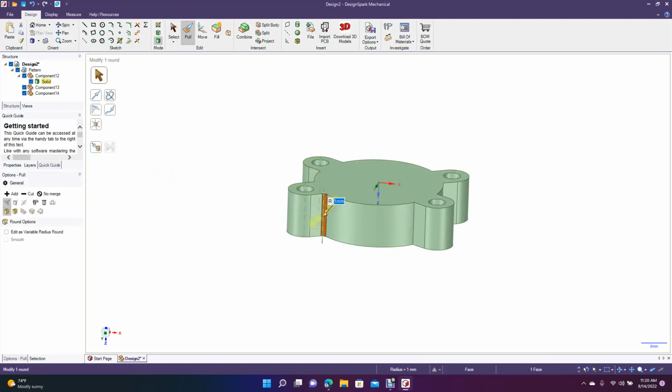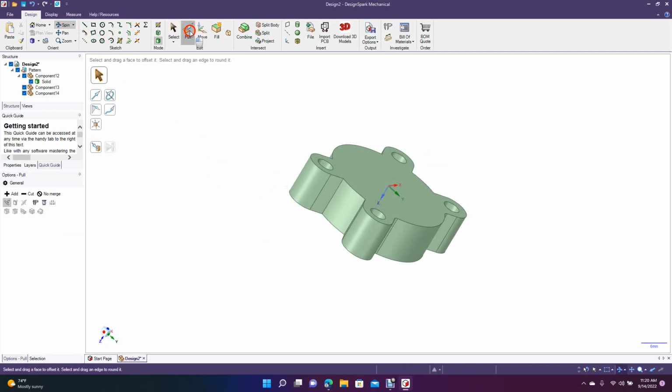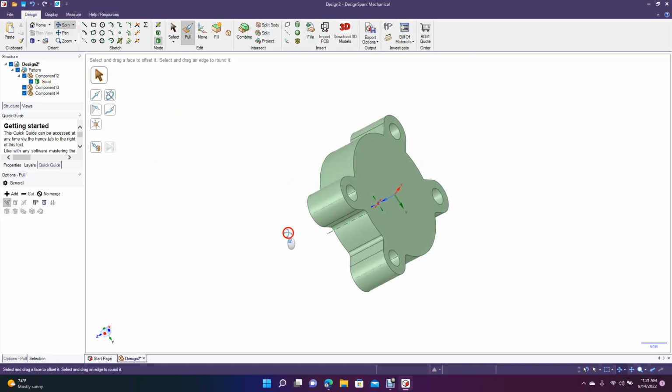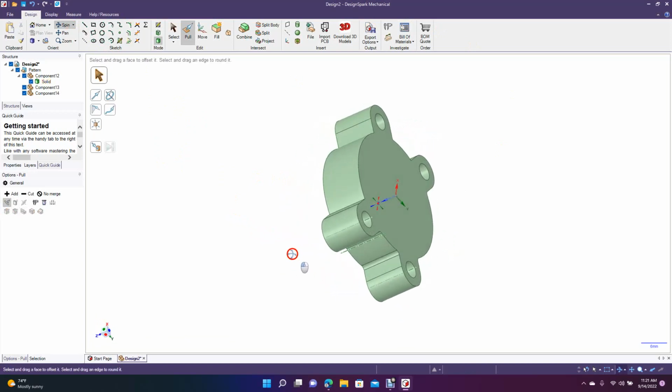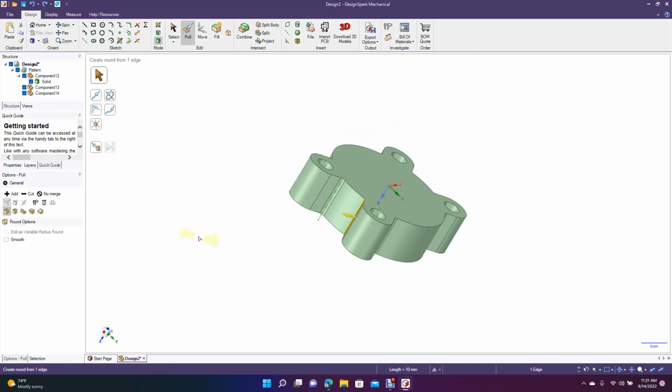There we can do a 1 millimeter fillet. And then in here, 1 millimeter on each of these. And you notice when I clicked on this, when it was a pattern, there wasn't anything showing up. So that means that you need to combine this stuff to get it to work. We'll go back and I'll show you what I mean. We'll do a couple of undos.